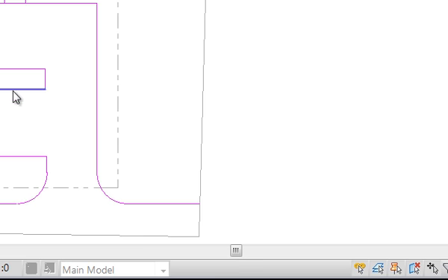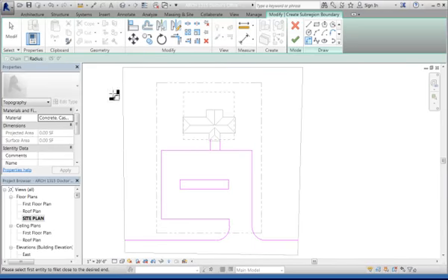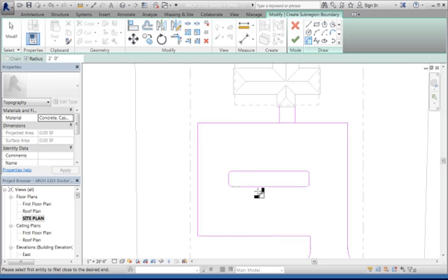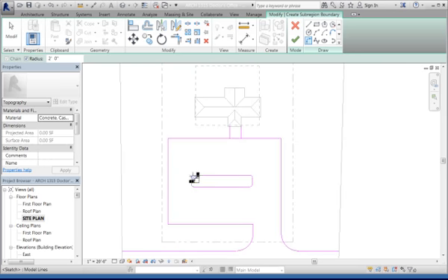So this is going to be your median, and the inside is going to be earth. So that's going to have a 2-foot radius on the turns. So I change my radius to 2 feet. I go there to there. I hit that one. Oops. Sometimes it does nutty things. So I'm going to do that again. Radius. There's that one. Hold on. Radius. There. Yeah, that's correct. Okay, so that's what it's talking about on a 2-foot radius.